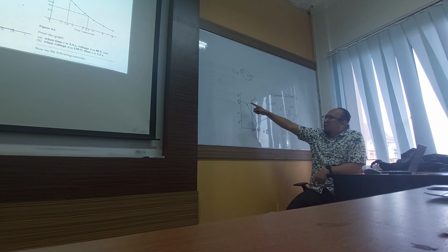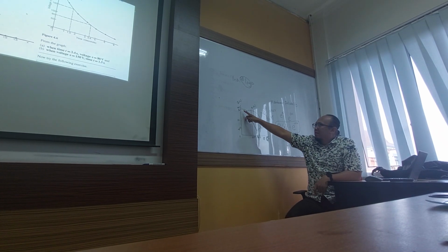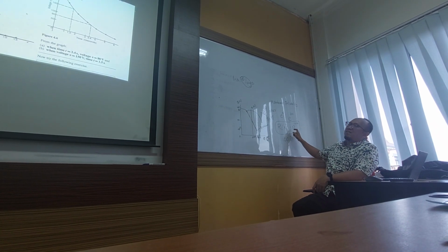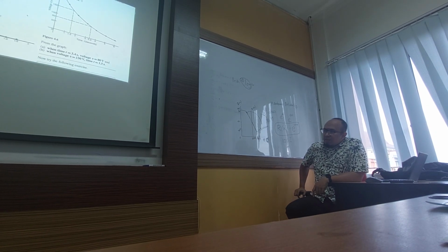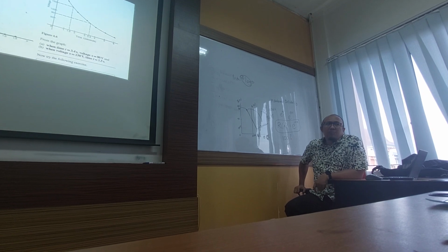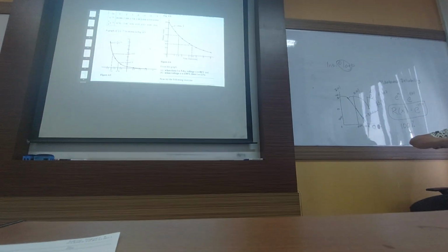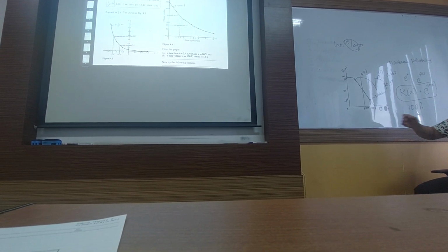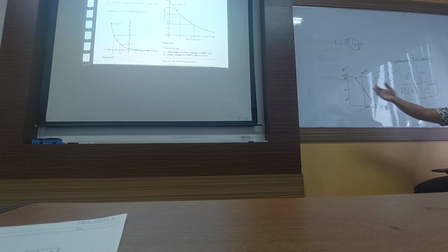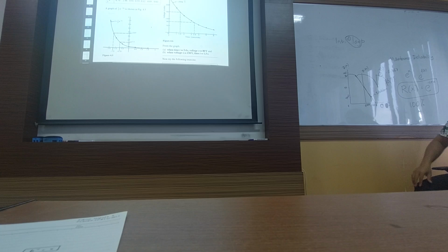So if you can predict the corrosion rate using the reliability function, you can use a preventive action, for example checking the thickness of the storage tank wall periodically, because you know that after several years the thickness of the wall will be thinner.